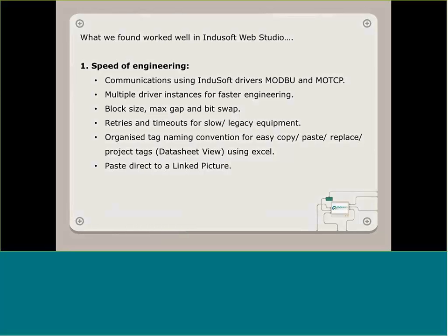Because we do so much Modbus integrating, we found that the Modbus drivers were fantastic. We found in a couple of instances for faster engineering that we could actually copy the Modbus drivers and use multiple instances of the same driver. We just found that using the main driver sheet is actually a lot quicker than having to use multiple sheets inside drivers. We could also do things like increase the block size when we knew a certain number of Modbus addresses could be read at once.